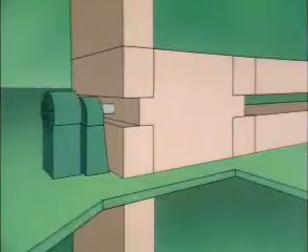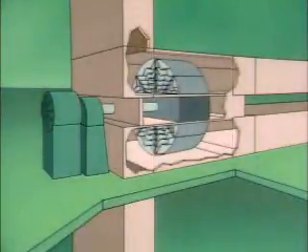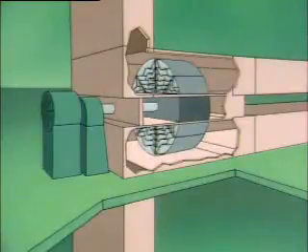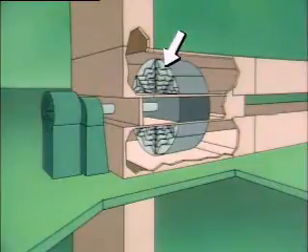In some boilers, the air supplied to the combustion area is preheated. Preheating the air raises its temperature closer to the point where ignition occurs. This, in turn, helps to ensure efficient and complete combustion. One way to heat the air flowing into a boiler is with a rotary air heater or preheater. This one consists of a series of heating surfaces or elements which are connected to a motor-driven shaft.